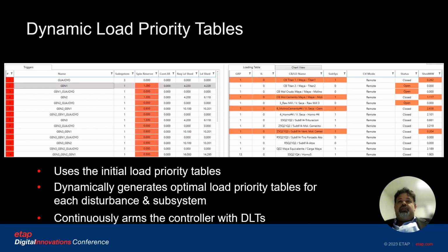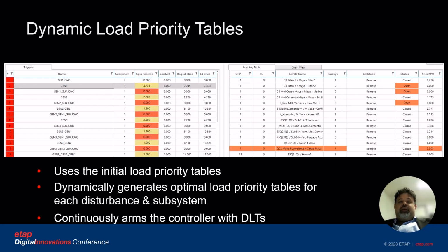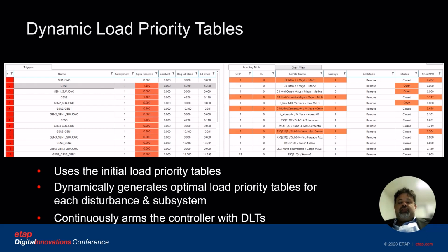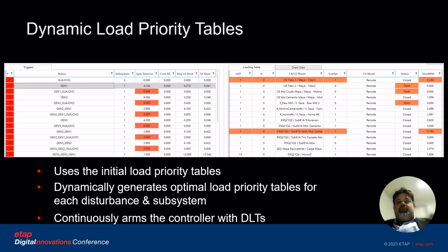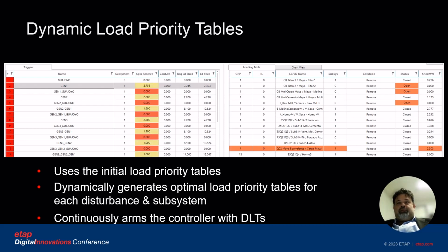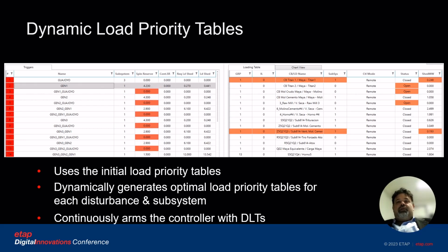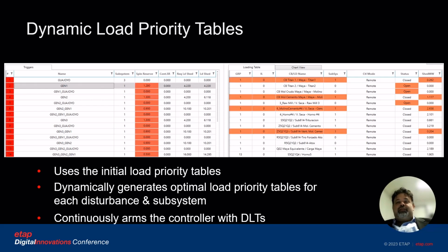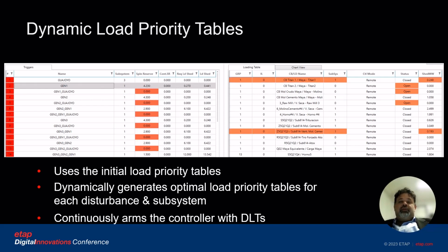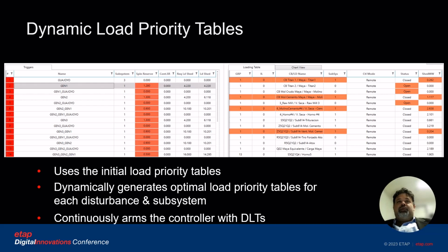Once this combination of loads is determined, the controllers are armed. When a condition happens, the controllers just take action based on the predefined combination of loads to shed. So although this process in the ILS controllers takes a couple of milliseconds, it will not affect the overall response of the system. Those milliseconds are not even part of the response time of the ILS, as this information is predetermined. So when a contingency happens, the action is just taken without any calculations happening in series.